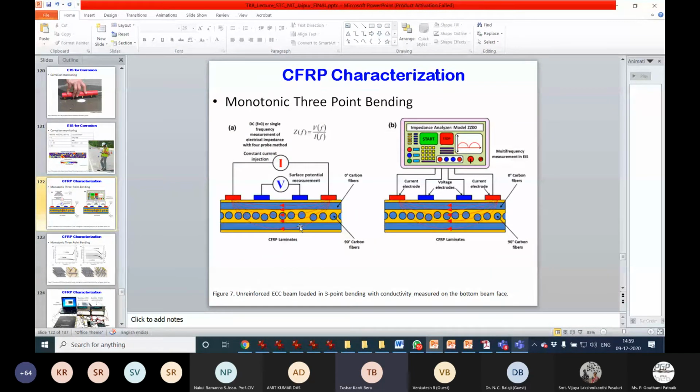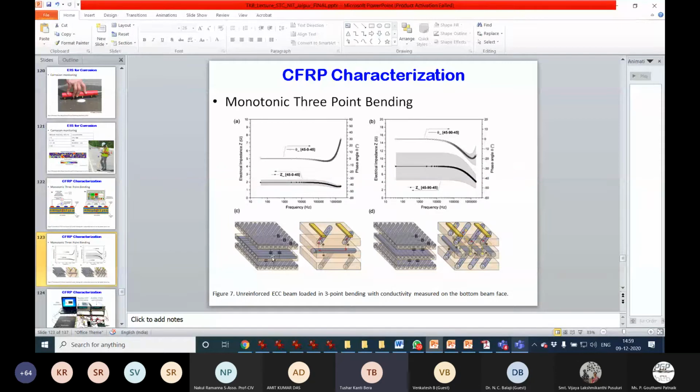The other technique I am going to discuss is CFRP, carbon fiber reinforced polymer. This is another material used in mechanical and civil engineering for structure development. CFRP is a very strong material, and its strength-to-weight ratio is very high. It is developed with carbon fiber laminates processed by machines where heat treatment is given, and the material is developed with different orientations of the fiber as shown here. There may be several angles of the fibers, so that we can get different kinds of mechanical properties.